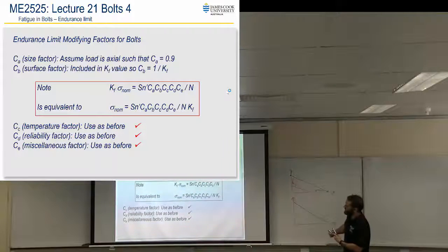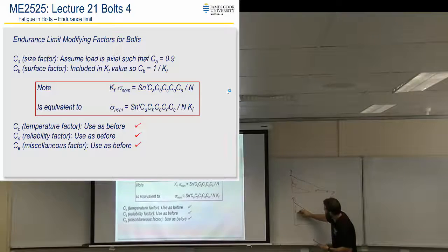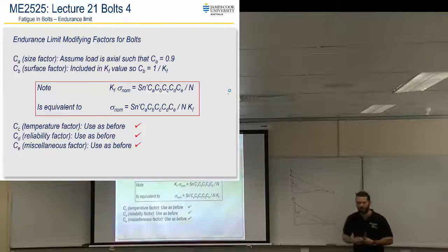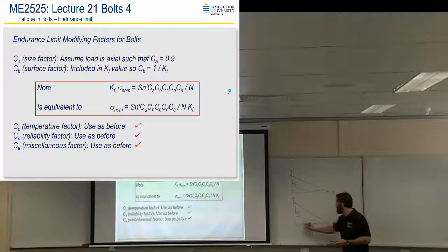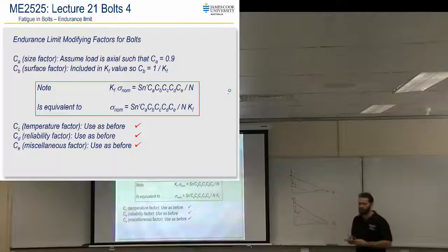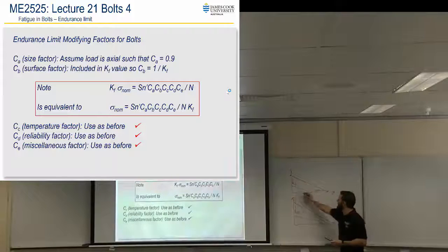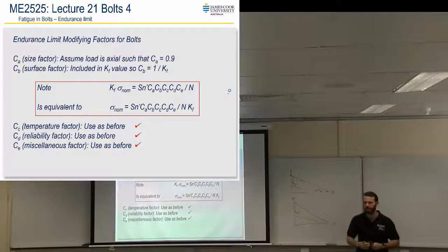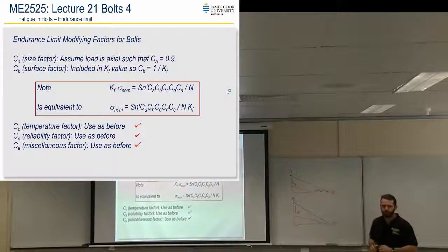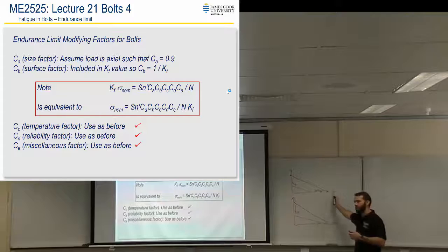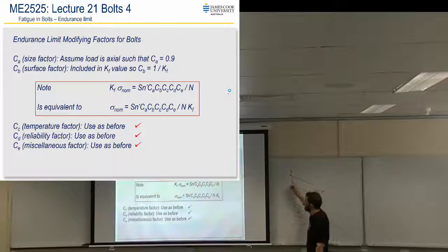now that we're only applying it on the fatigue side, we're effectively bringing that, if it's 3, bringing that down by 3, but we're not doing anything to that other end. Which means that when we come over here on our pre-tension, we've not screwed everything up. So if we did this and came over here on the pre-tension, we're already counting that as failed. Okay? So because things yield locally and yield isn't a big issue in static failure, we can actually do that and just apply the stress concentration to the fatigue side.